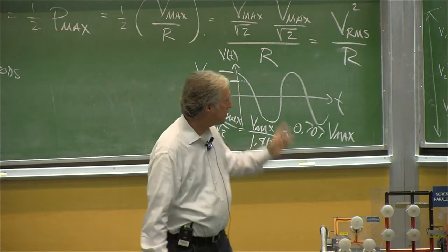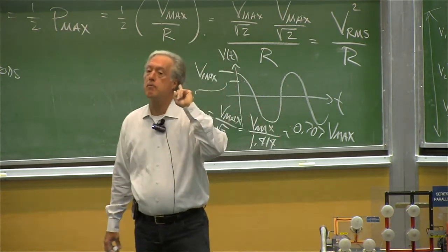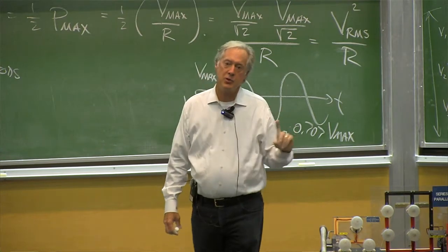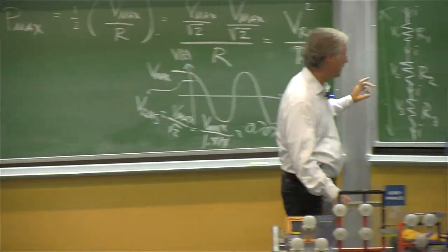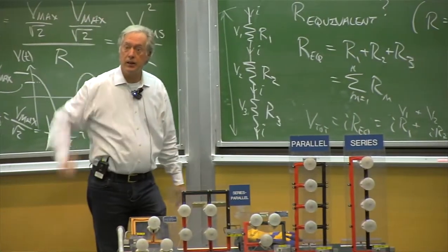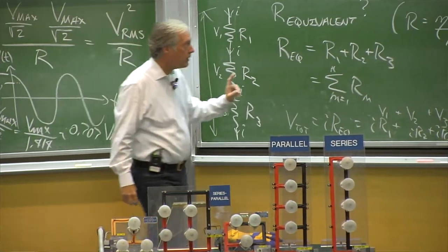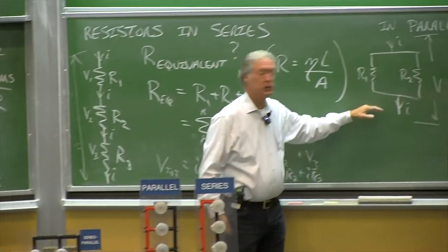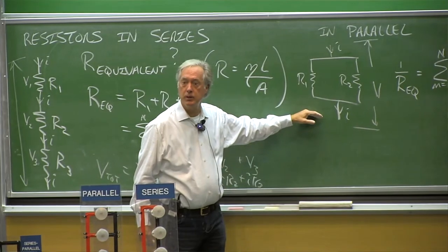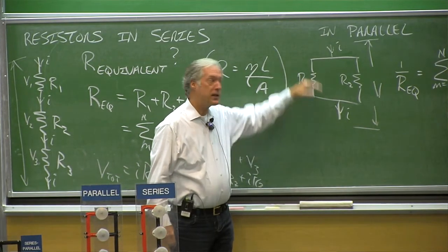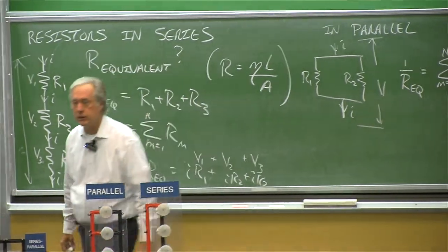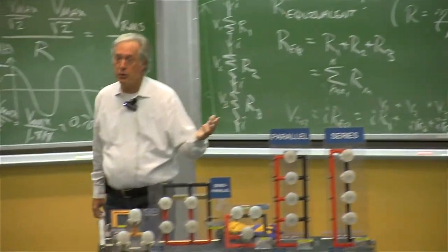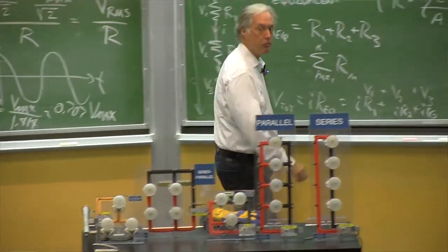No. So those lights are wired in parallel, and that has two functions that are really nice then. If you wire your lights in parallel for overhead lighting, they all have the same voltage applied to them all the time. So if they're all designed to be 120 volt lights, then you've got 120 volts at every bulb all the time.